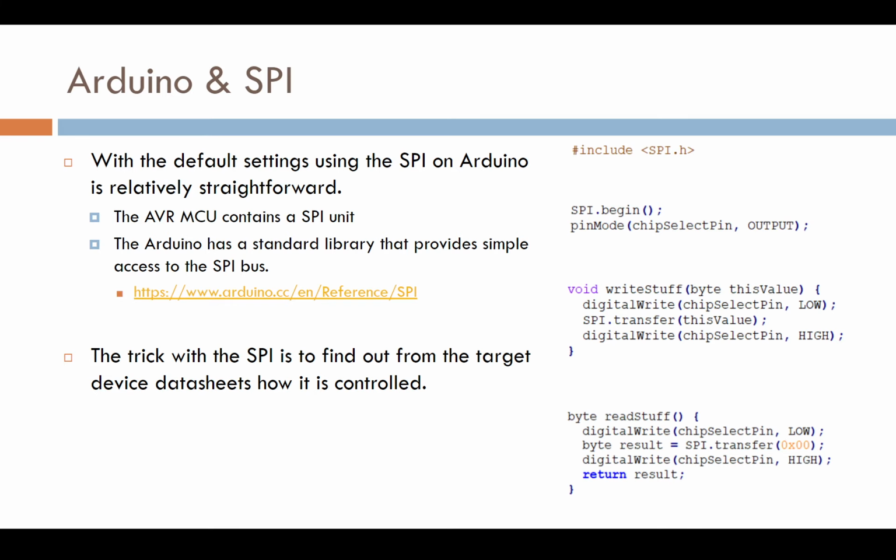But the fundamental parts are: start transmission, set read or write, set a certain address, then if needed restart, and then do the second operation. Usually you first set a command, which is writing a command to a device, restart the bus, and then set the address again to read data from the device. Okay, that kind of protocol.